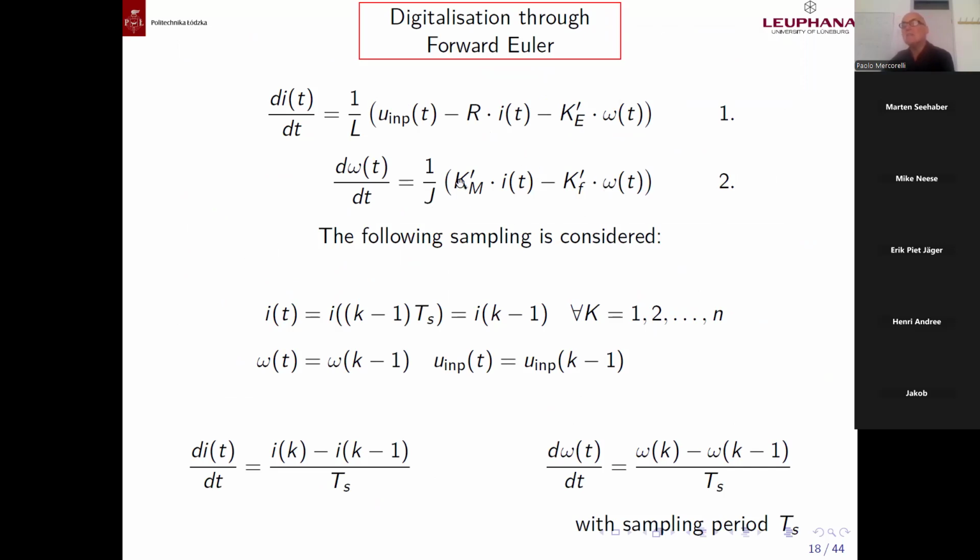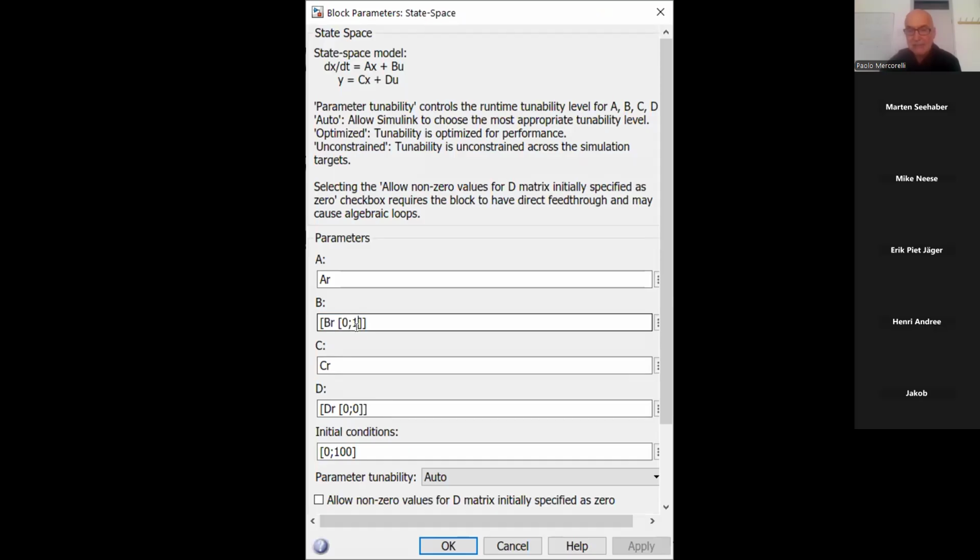Here, the balance that you have is a torque balance. It's divided by J. This means this is not exactly correct. I have to divide by J, but I think it's no problem because we didn't test here with the disturbance. The matrix D consists of 2 rows and 2 columns, because the matrix D has the same rows as C and the same columns as B. We consider initial conditions in order to check the controller.